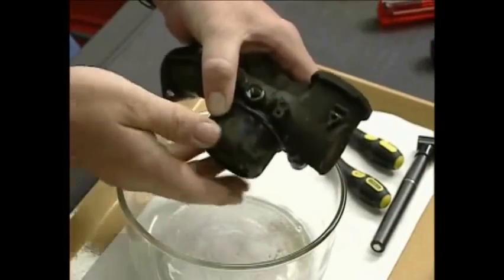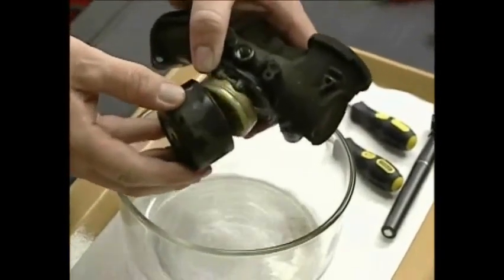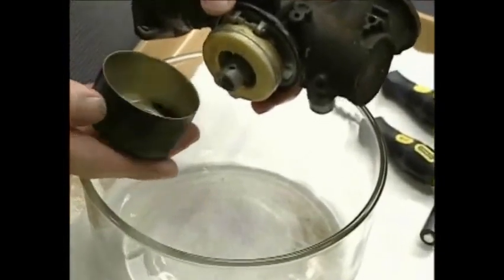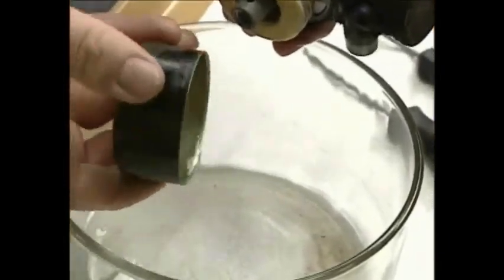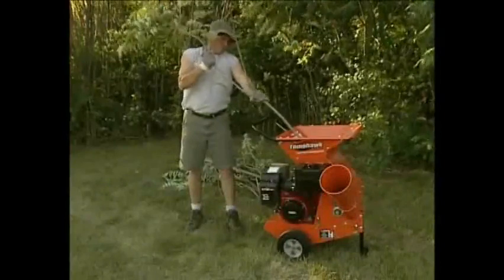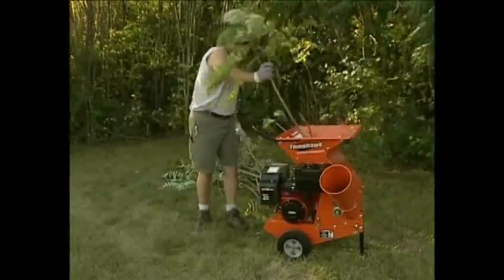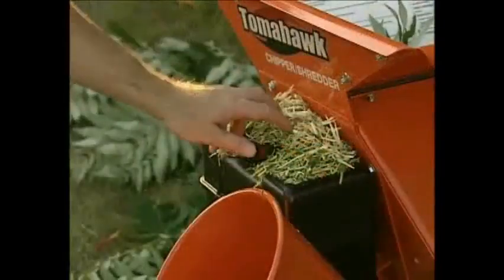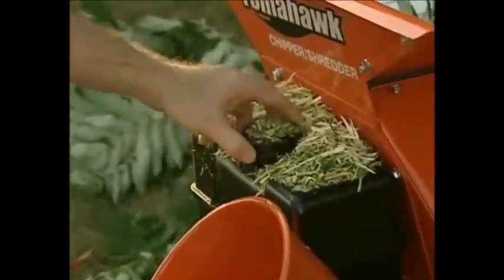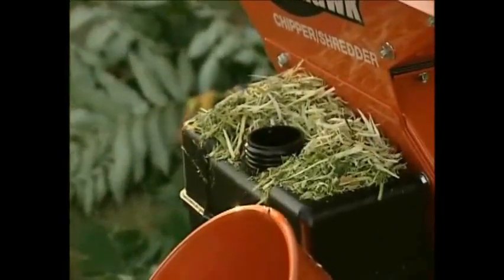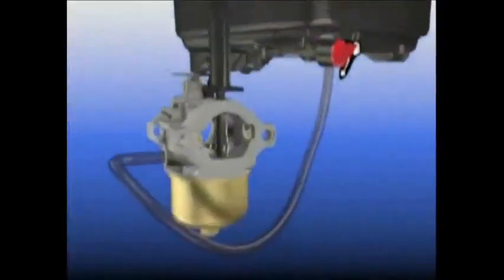Dirt and debris has been and continues to be the #1 problem for carburetors. We need to better understand what dirt or debris is and where and how it enters the carburation system. Dirt is a natural substance that can find its way into the carburetor through the air intake or dislodged gaskets. Dirt can also enter through the fuel system when the customer removes the gas cap, or directly from a contaminated supply tank. Depending on the type of fuel filter being used and the size of the particles of dirt, the carburetor may never be affected.